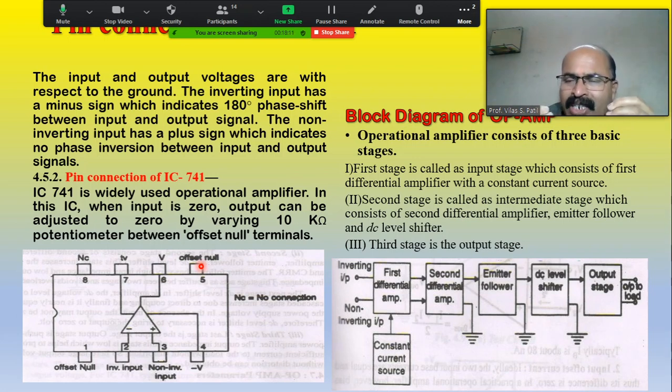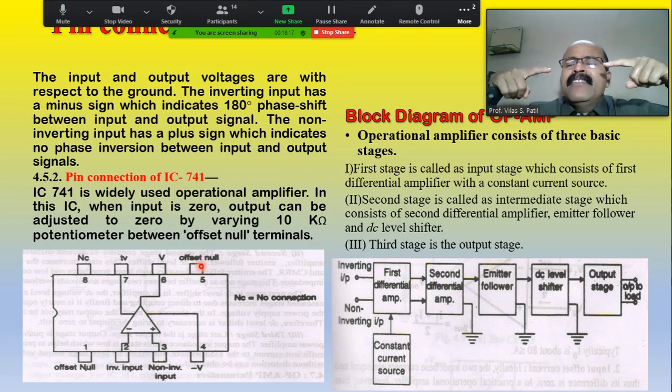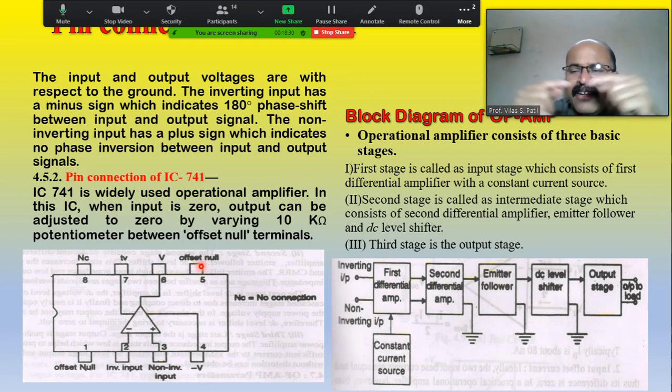some deflection or some difference between the two transistors, then the collector voltage in both the transistors is not the same, and there is some difference, that is, the magnitude of the collector voltage appearing in both the transistors T1 and T2 is slightly different, and we get the sum of the voltage across the collectors of both the transistors.